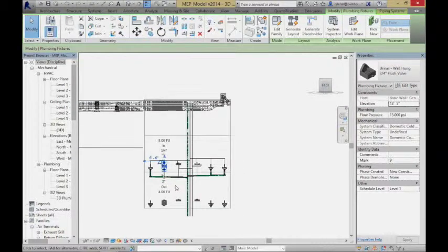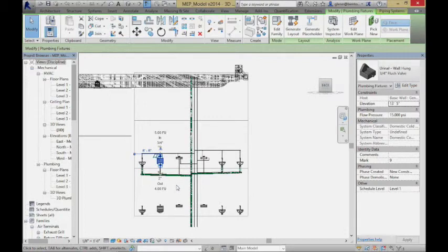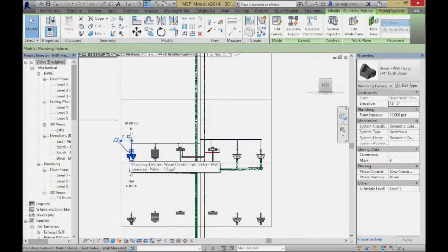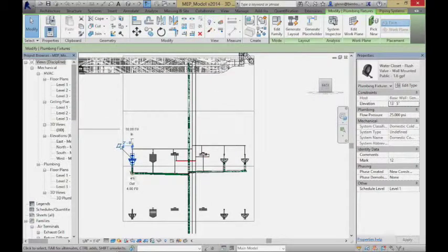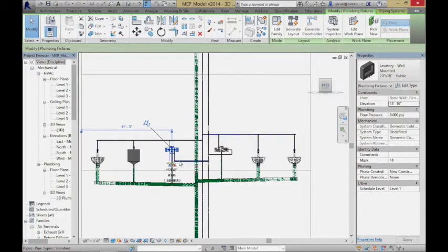It's a 2-inch outlet. If I go to the toilet, you'll see that it's 10 fixture units in and a 1-inch pipe, 4-inch out, contributing 4 fixture units. The way fixture units are measured, it's different for the supply side and the output side. If I go over to the sink, you'll see it actually has a couple different ends.